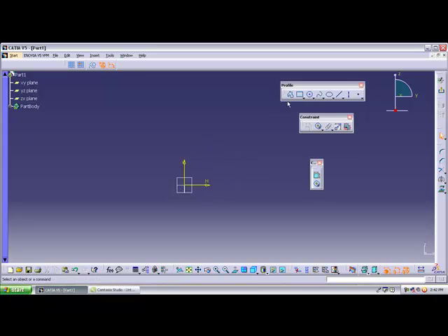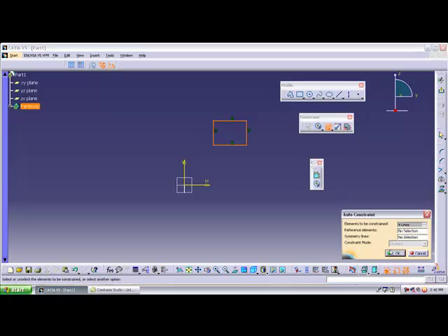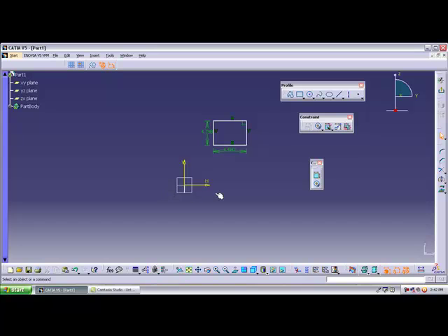Let me check it. Right now I am drawing a rectangle. After drawing the rectangle, what constraints can you apply? That is the length and width. After that, where is the rectangle in the plane? So what you can do is select the rectangle and select the automatic constraint. In the fixed together submenu there is the automatic constraint, and click OK. See, what constraint dimensions do you get? You get only the horizontal and vertical dimensions, but the object is fully constrained.